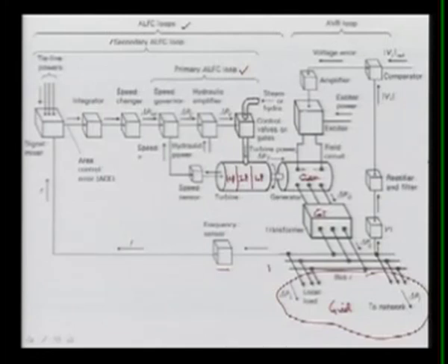Also here we are measuring the tie line power flow. You remember that we require the tie line power flow as well as the frequency when I was discussing the AGC logic. So here we are measuring the tie line power flows, meaning the areas where they are connected, what are the various tie lines, and then it is a mixed signal. Finally, from here this block is nothing but, if you remember, it is giving your area control error ACE, as in the previous lecture.